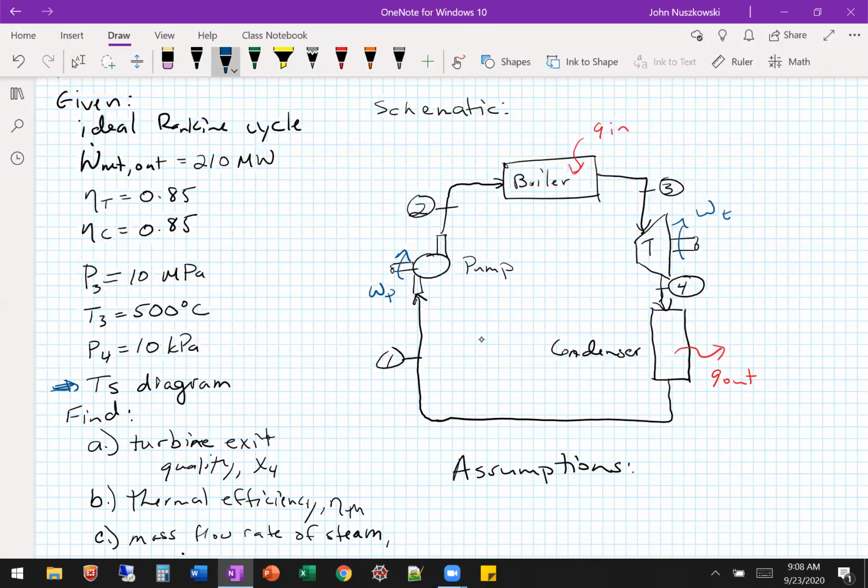The question. So the ideal Rankine cycle is the same. So it's pump, boiler, turbine, condenser. So just like in the Brayton cycle, we had compressor, heat exchanger, we're adding heat, turbine, other heat exchanger to reject, right? So it's kind of the same setup, except we're raising the pressure of water instead of gas, so we have a pump. All right, and then we're changing phase, so we call it a boiler, right?